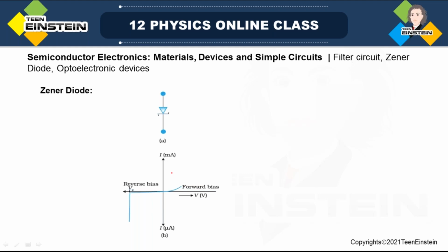See, this is a very sharp change. It is changed like this. So the voltage here in the Zener is almost not changing, but the current change is there. Suppose here it was 10 microampere, here it becomes some 50 microampere, here it becomes 500 microampere, but the voltage change is very small, or almost no change. So this is a very special property of the Zener diode, and this property is being used.